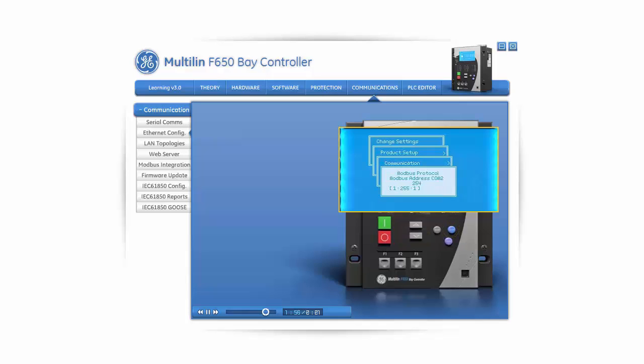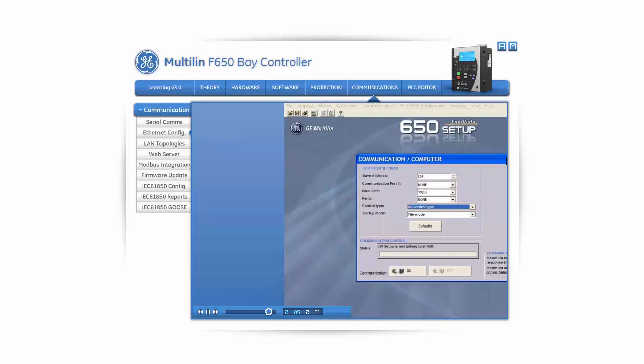In order to be able to communicate, the following considerations must be completed. The relay IP address and the computer IP address must be different, but both subnet masks must be the same. This way, both elements are identified as different elements in the same network. For more information concerning which IP addresses to use, refer to your network administrator.